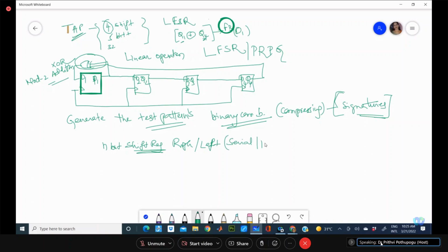These were the operations we have seen as far as the shift register is concerned. But now, taking this feedback element, we are able to generate a sequence. That means this shift register circuitry is a little less complex. If you use a counter, you need a clock segment and a conditional output coming over. All this one-step complexity will be more to generate a sequence, or the combination of bits. So for that, maybe a shift register with a simple feedback element.